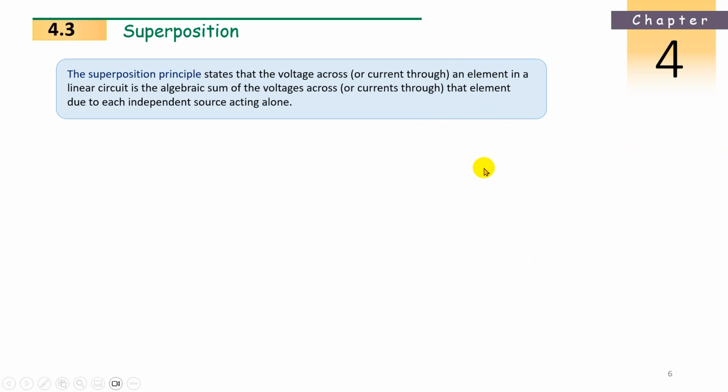So what we can do is, at a time, take only one voltage source and remove all the remaining ones. Now the circuit is easy. When you remove all the other voltage sources, only the resistances remain. The resistances can be solved by series-parallel combination: 2 are in series, 1 is in parallel. Then only one voltage source is there, so we can find the current with Ohm's law, then divide it into the other branches. We will get the currents. That is the first step.